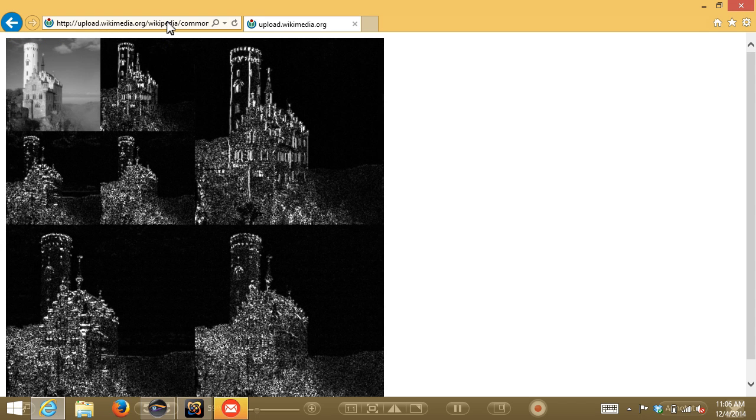Okay, so what you're seeing here is, this is not really the best example, but here is basically the effect of a 2-level wavelet transform, right? These are the edges that are most important at the highest level. This is like if I high-pass filter the signal twice in both the vertical and horizontal direction. And then here, these are the high-pass edges that are most important at the original resolution in the left-right direction. For example, I have a strong edge in the castle here that's coming out as strong edges here. And then these are the edges that are most important in the vertical direction. So for example, the top of the castle responds strongly here.